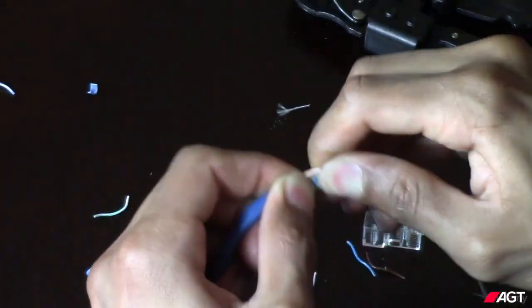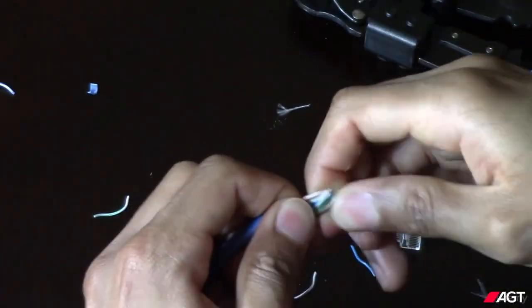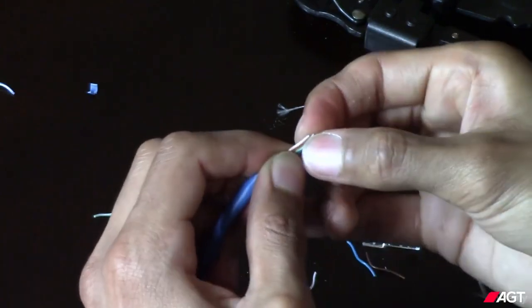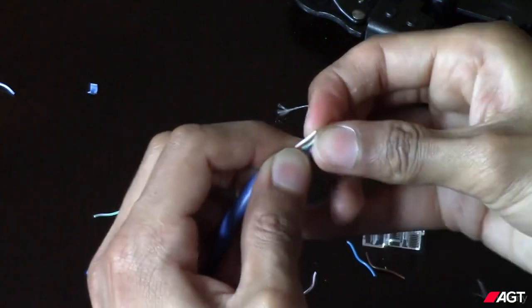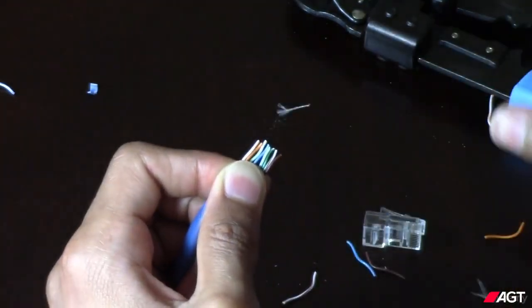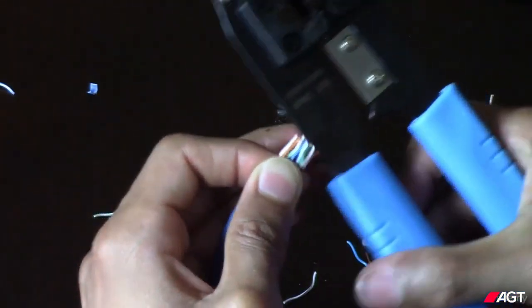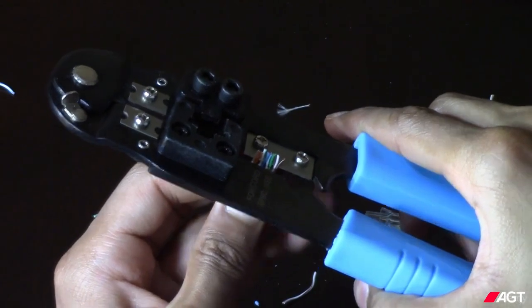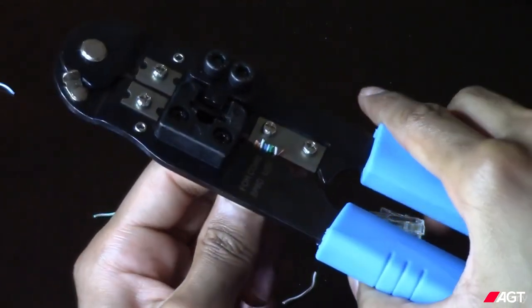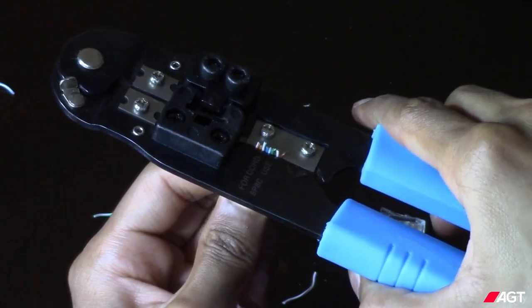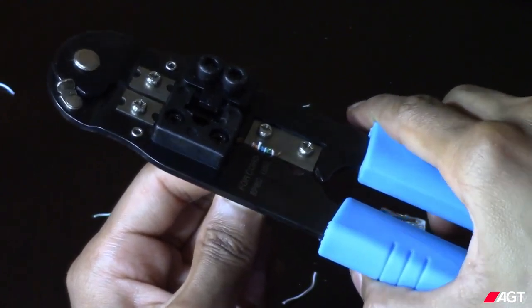Grab them by the end and give them a few gentle bends to ensure that all the wires are neatly flattened. All 8 wires have to be in a neat row in order to fit into the connector. Give the colors a quick review and make sure they haven't shifted. Then insert them into the bottom blades of the crimper tool with a very little amount, like 2mm sticking out the other end. Now press down on the crimper, but don't squeeze so hard that you cut them.